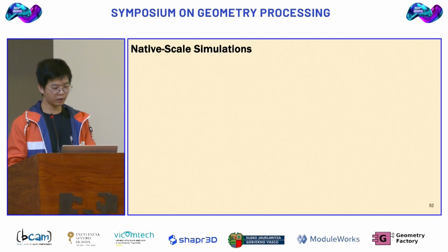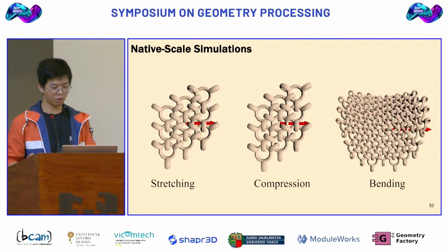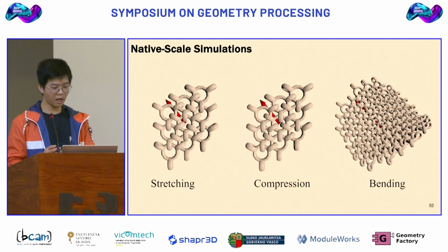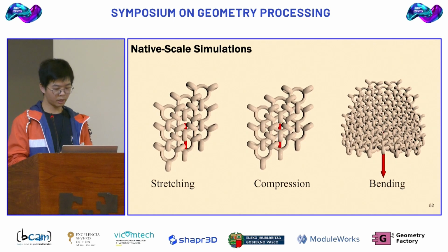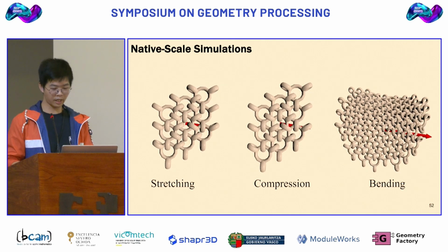Okay, so we can then deform the structure to obtain the mechanical properties of the material. But unlike elastic materials, discrete interlocking materials can freely deform in a given direction until a hard stop due to tight contact between elements prevents further deformation. So instead of deriving elastic properties, we derive deformation limits of the materials. We observe that discrete interlocking materials can be fully described by enumerating all feasible macroscopic deformations. Therefore, for each material, we perform many virtual deformation tests for uniaxial and biaxial stretching and bending in different directions.